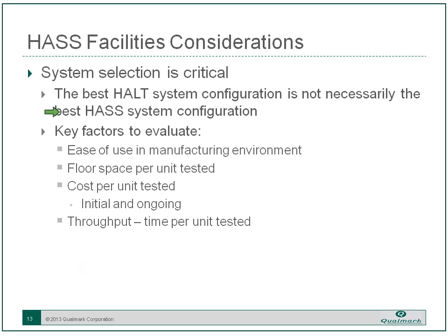Now, selecting the right system to do HASS in is critical. You may have a HALT chamber or have used a HALT chamber in a lab that is certainly adequate for doing the HALT in, but it may not be the best HASS system configuration. There are systems better for high volume HASS, depending on product configuration.